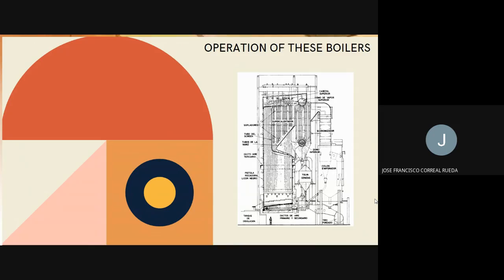The saturated steam, in contact with water, leaves the steam dome towards the superheater, where it increases the temperature above its saturation and leaves the boiler toward the process and or is used in a turbine which rotates and produces electricity. Recovery boilers have these characteristics: they are stationary with an internal ignition furnace, two drums located transversely with simple gas passages and natural water circulation. They are proposed to generate steam and recover chemicals present in the fuel.